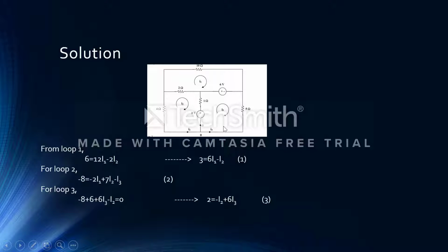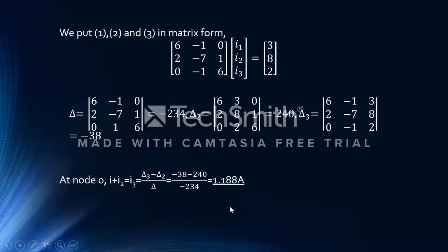Now for loop 3, we simply get the equation minus 8. We have this voltage and plus 6, and then we have I3 over here, 5 plus 6, so 6I3. But here the I2 current also flows through this resistor, in the opposite direction of I3, so minus 1 times I2. On simplifying the equation for loop 3, we get 2 is equal to minus I2 plus 6 times I3.